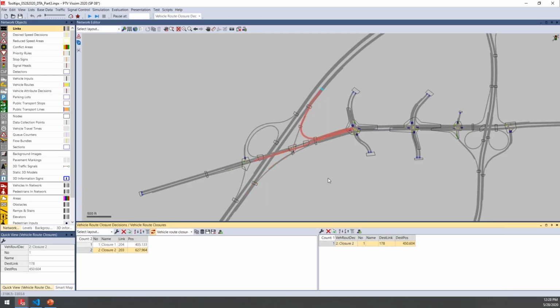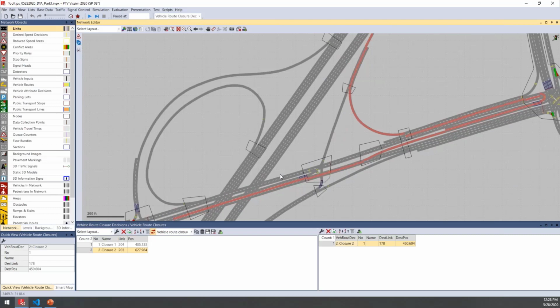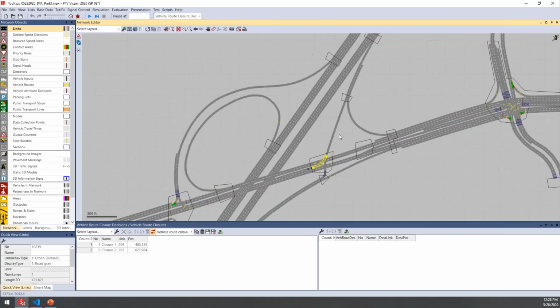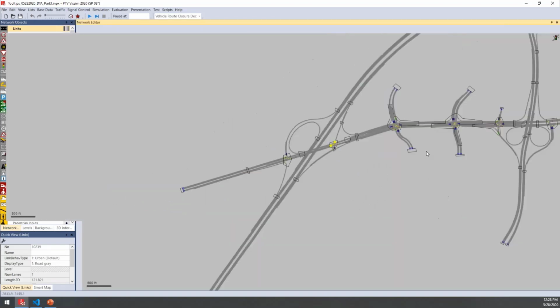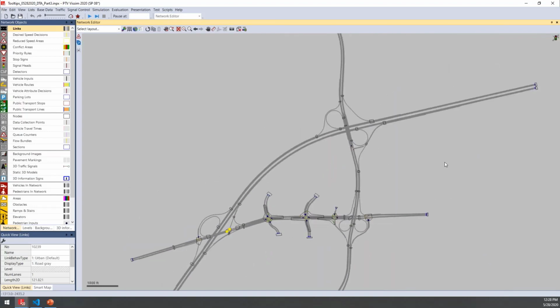And then I have a second one that here, for any of these vehicles that were kind of making this U-turn to try to get to the freeway, instead I wanted vehicles to take this other path that would just take this regular turn to the on-ramp. All right, and then as part of the upload, once we have completed this webinar, we'll include this file as well as another file that does have that dynamic assignment kind of deactivated so that you can go ahead and compare both of those networks.